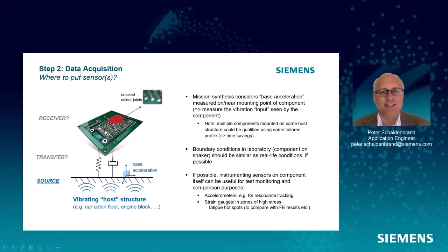Now, if at all possible, it's good to take some data on the structure itself so you can get an idea of fixtures. We like to mount it with the same mounting impedance that it has in the structure, but a lot of times in the field, that's not possible.